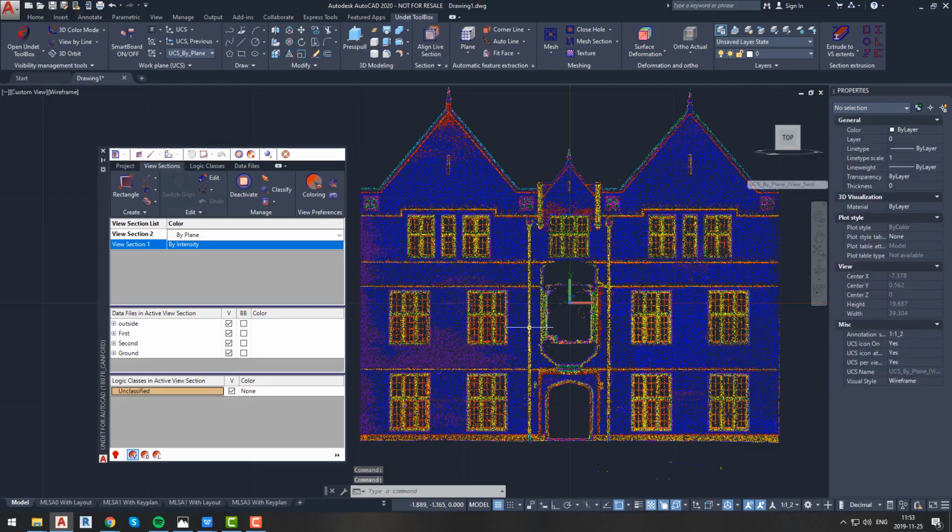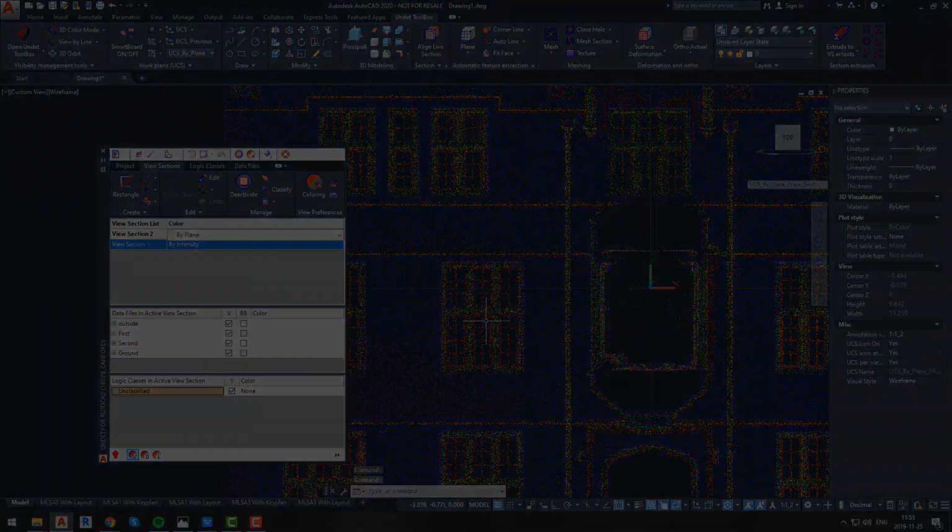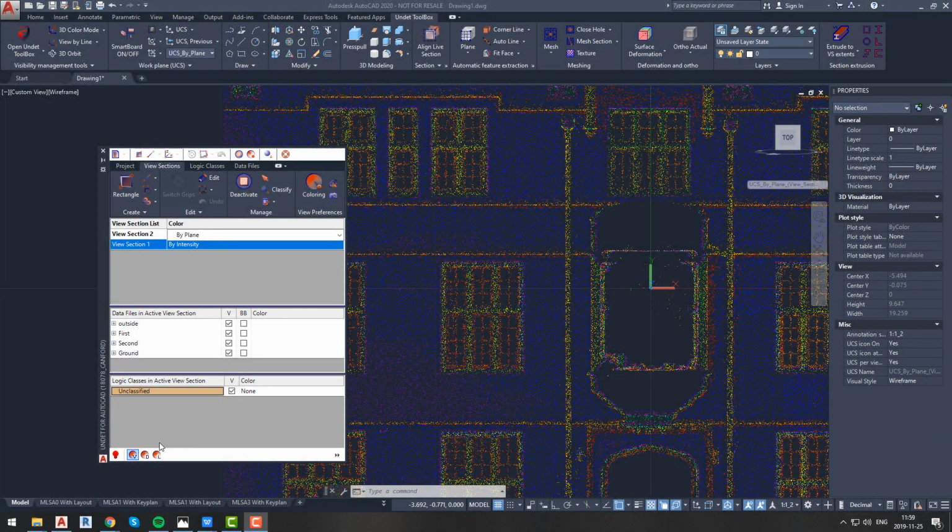Now we can see a very detailed view of our facade, but we are not seeing all scanned point cloud points. To know if you are seeing all points or preview points, Undet has a View Mode Indicator. It is located at the bottom of the Undet palette. The indicator can be red, yellow or green. In our case it is red. If you change density to 100%, it will allow you to see all preview points grid.